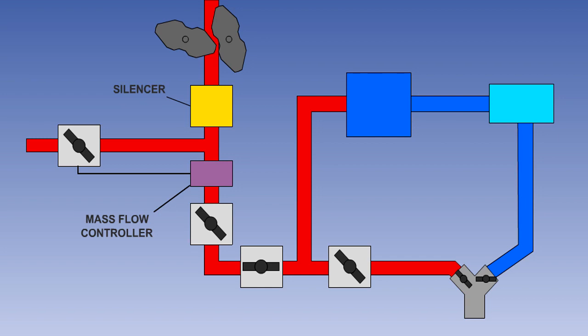The blower must be capable of supplying the required mass flow of air under all operating conditions, which means that at high engine speed and low altitude, too much air is supplied. A mass flow controller signals a spill valve to vent the excess airflow to atmosphere.